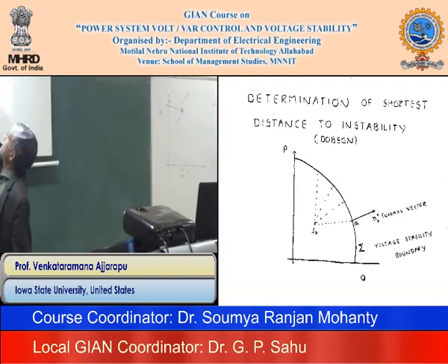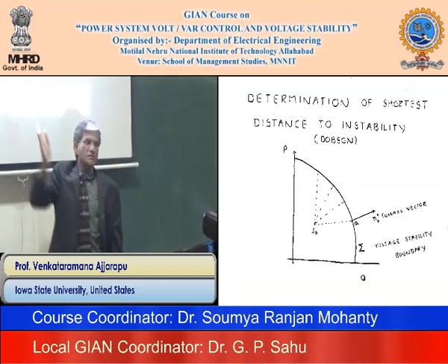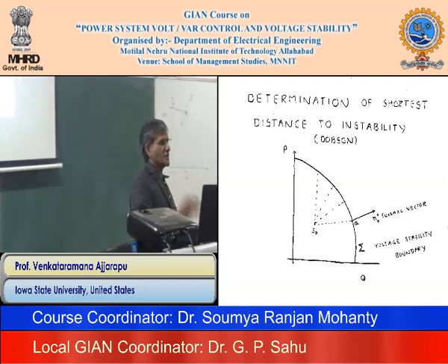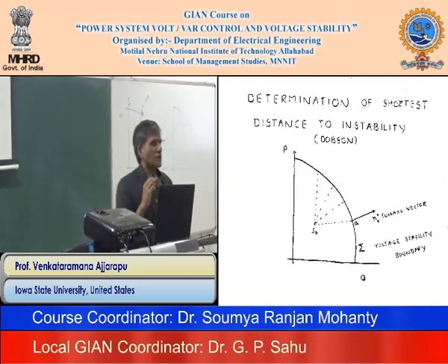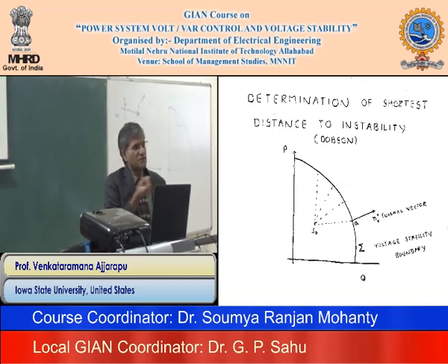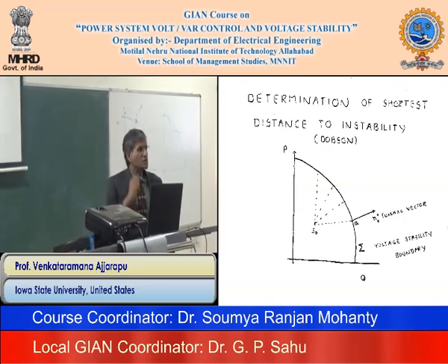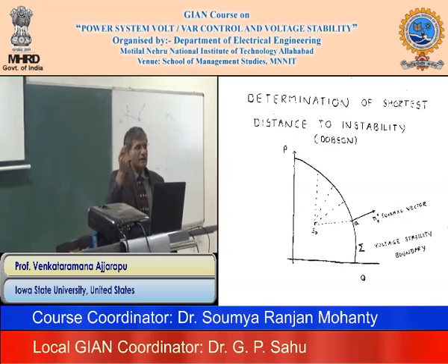So basically you iterate on that, where this N0 becomes your load increase there. Then you will stop. So first you need one boundary point, calculate the normal vector, and check that the normal vector is the same as your load increase direction. If it is not, take another one close to the normal vector, and then increase again and iterate. When both are similar, then you stop. I think that's the basic idea.